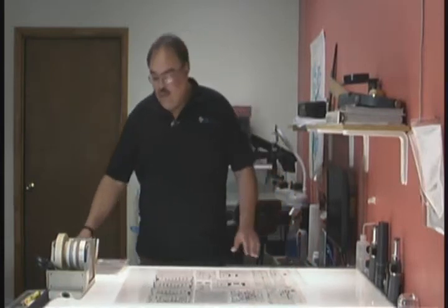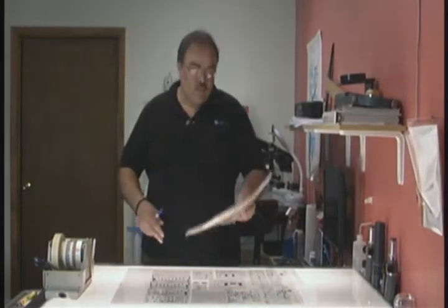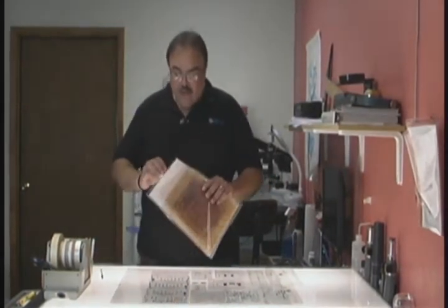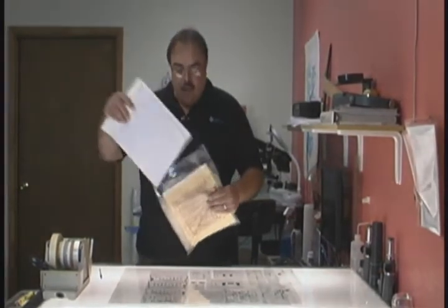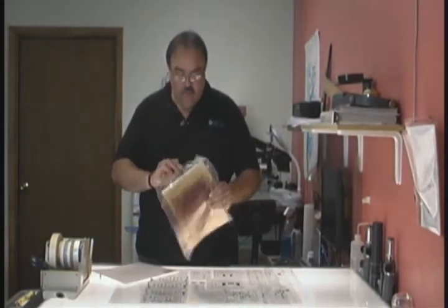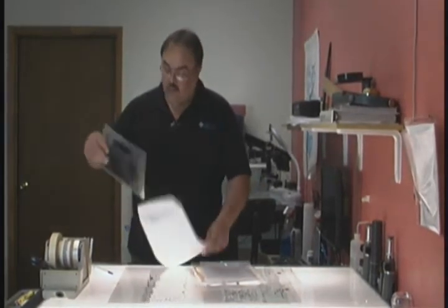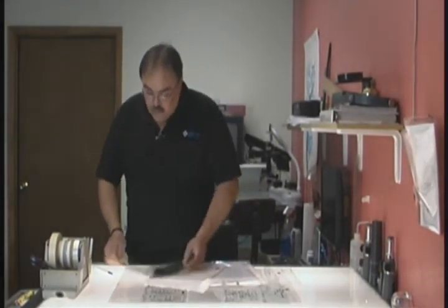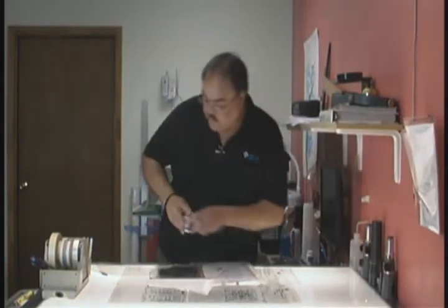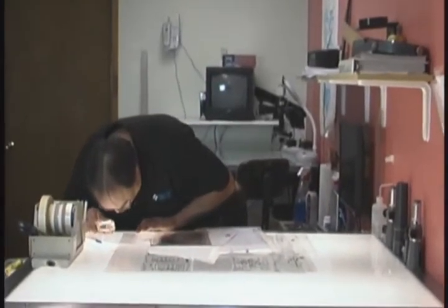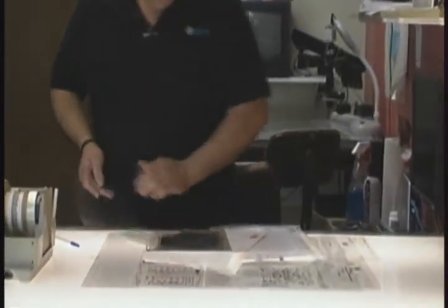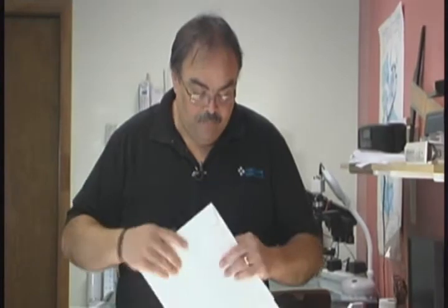The first step that we do, when we receive the package, is we compare what we have here with what was originally quoted. In this case, we quoted for four layers, 2 masks, 1 silk, 7 pieces of film. We've got to make sure that they're here. Then we will take a closer look at the film to make sure that the quality of the film is acceptable for our process. If there's any problems, then at this point, this is when we will contact the customer and let them know what's going on with the job.